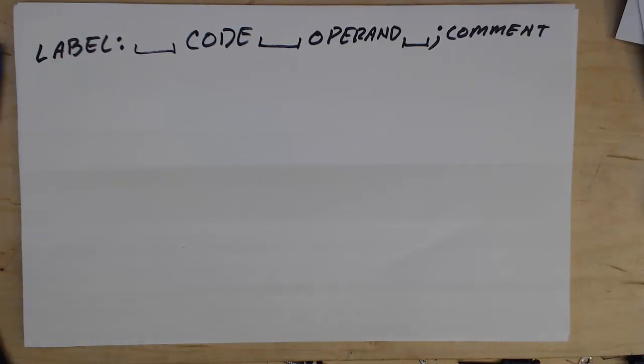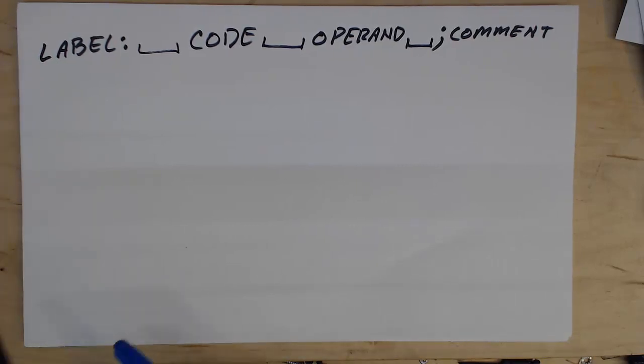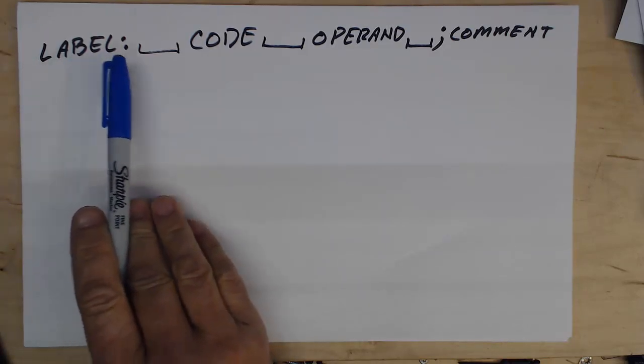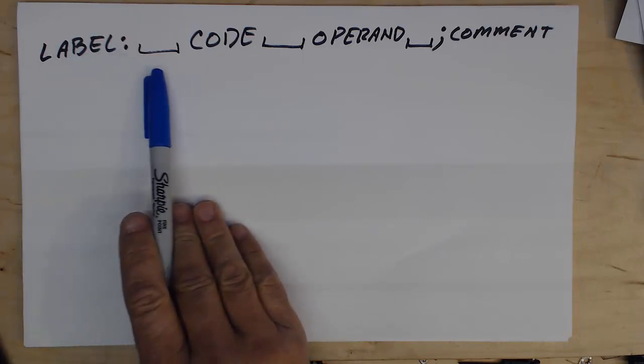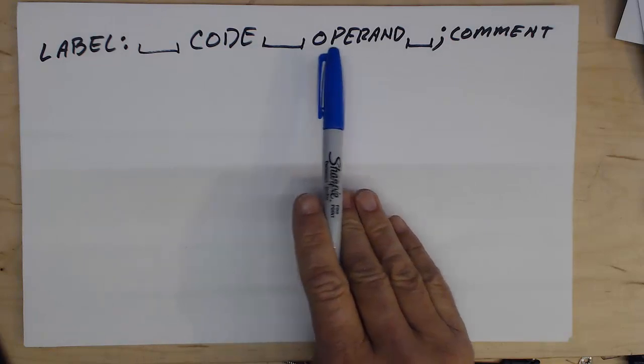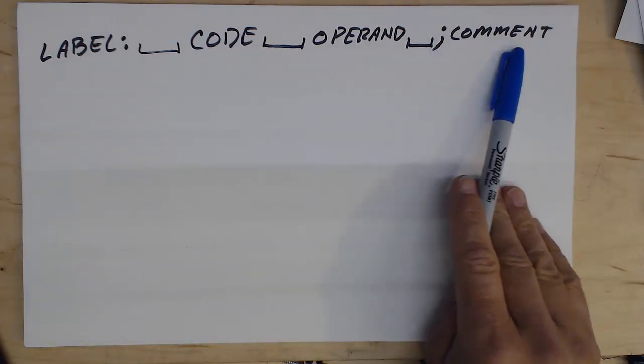Let's talk more about the assembly for the 8008, and we're going to start today by looking at the syntax of a line of code. So this is our line of code where we left off last time. We have our label, which ends with a colon, and then we have some white space, and then we have our code, which is going to be our mnemonic, more white space, our operand, white space, semicolon, and a comment.